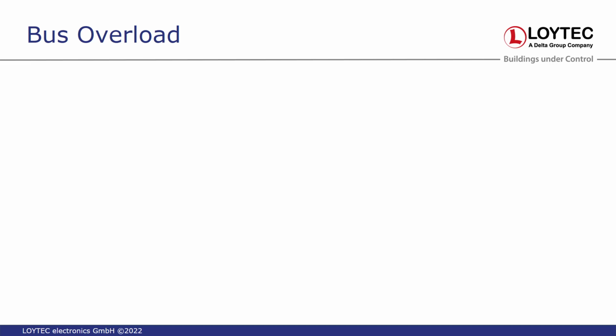And the second thing is, in that case, you would need to add a second power supply or a stronger one or whatever. But there must never be more than a 250 milliamps power supply on the channel. That's the maximum the ballast and the devices can withstand. But the second thing then is how many logical addresses you have available. So how many lamps you can address. That's a logical thing, how many short addresses you can assign. And here the limit is 64.